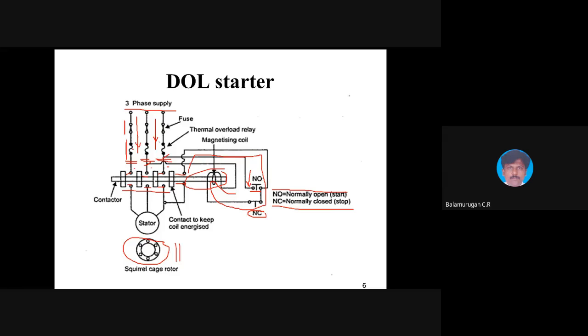And rotor copper loss Pc is equal to S into rotor input. We have derived all this already. So Pc equal to Pcu equal to S into the rotor input P2. From this we write the equation 3 I square R equal to S into K T. Here we consider R2 as a constant, so this 3 will be constant, so K will be constant.